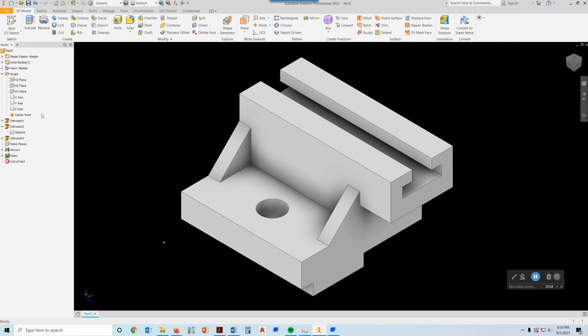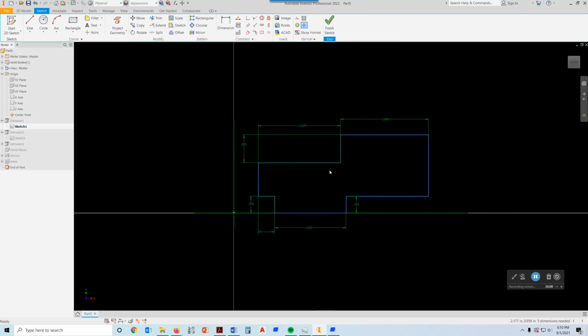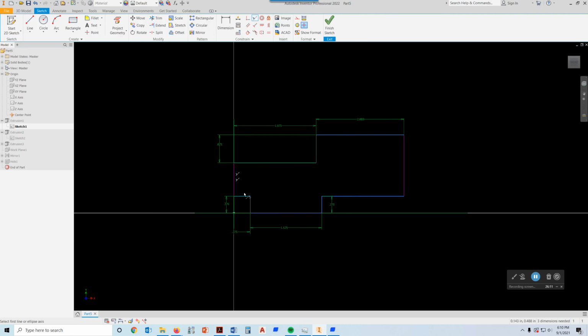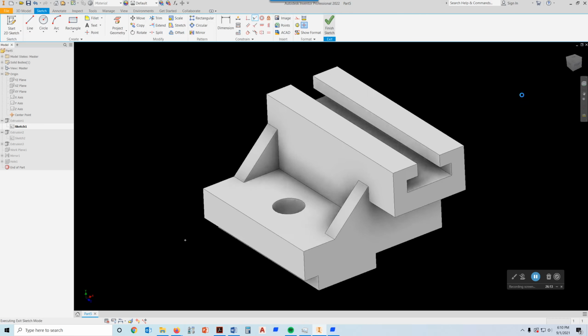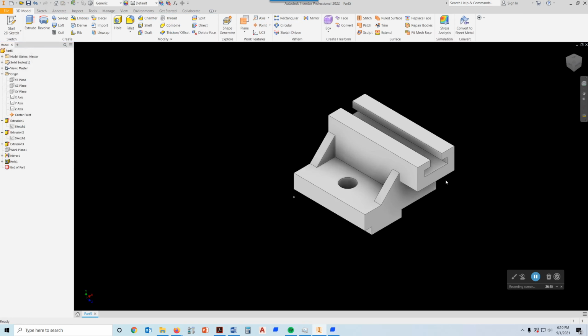And so remember that anything we need to change over here, if it's an extrusion, we expand on it, we double click on the sketch, and then we just edit the sketch. Now, one thing I could try to do on this guy is use the collinear constraint now and pick this front edge right here and then pick, and that moves that, and then we pick finish, and it actually moves our part, but we don't see much happening with the part.